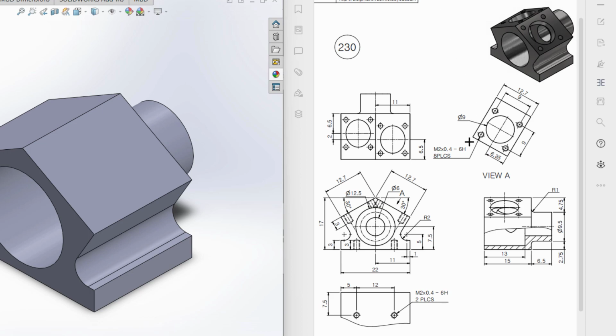Now for that, we can see here to here the distance is 9 unit, and here to here the distance is 9 unit. And for a reference geometry for this spherical cycle, I will take a center rectangle and draw a center rectangle here having 9 by 9 dimension. Then I will make the rectangle construction geometry, then use all the corners as reference points for the hole wizard portion. Okay, then finally